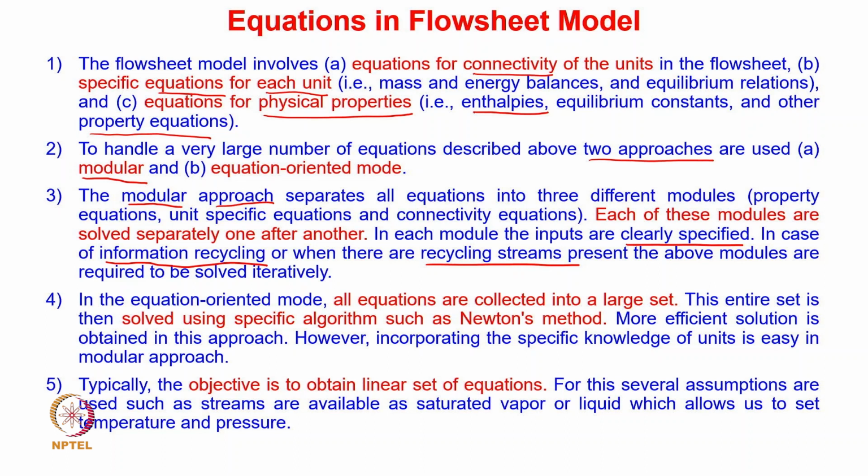In contrast with this, the other approach we are talking about is the equation oriented approach. In the equation oriented approach, we collect all the equations into a large set: the equations for connectivity, the unit specific equations, and even the equations for properties. This entire set is then solved using specific algorithms, like Newton's method. Clearly this second approach is more efficient, because you are looking at all the equations together, and therefore a more efficient solution can be obtained.